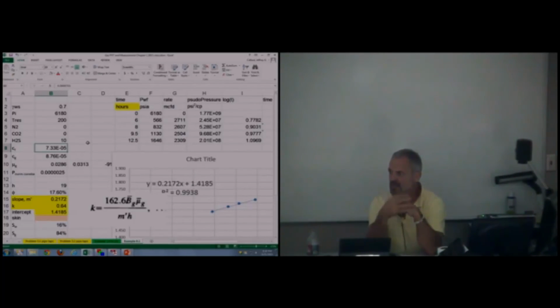Isn't it very similar to that of methane? Methane is about 16. So I can understand how the textbook is getting away with it. They couldn't do that with CO2 or H2S because the molecular weight is so much different. The gravity would have to change considerably. But they're close enough that, whether it had 8% or 12% nitrogen, it wouldn't have a grave effect on the gas gravity.